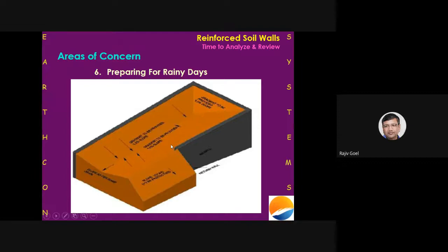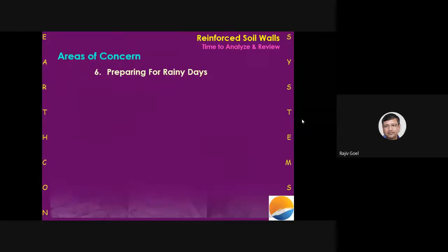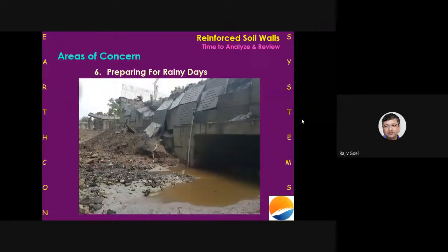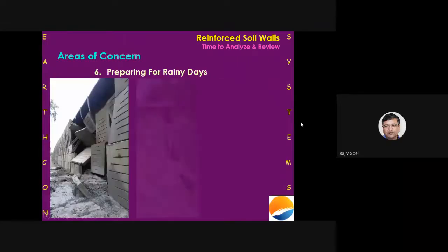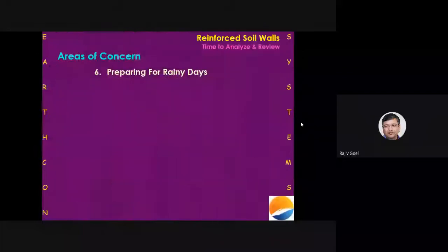So it's very, very important for everyone, and we keep writing in our drawings in very, very bold terms that proper discharge of rainwater has to be taken care of. But in spite of all this, problems do happen, and we face it. And mind you, for all these constructions which I showed you, the only repair is reconstruction. There is no way that you can put these panels back and fill back your backfill.